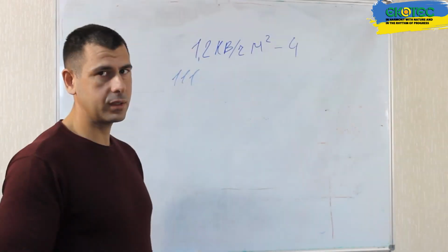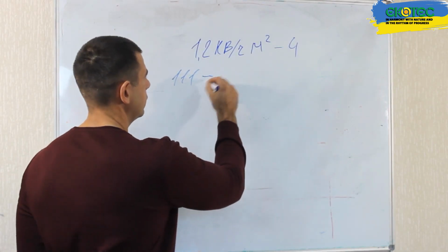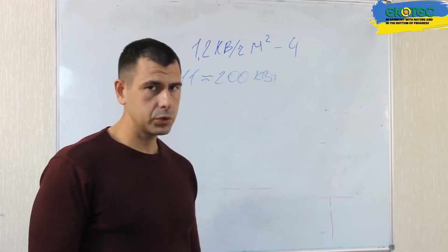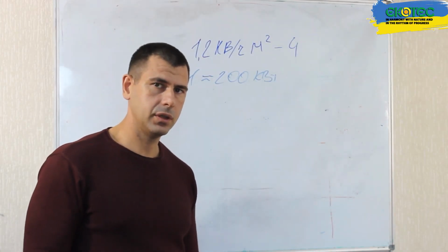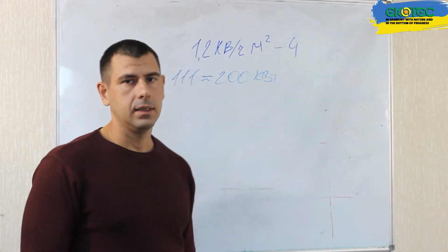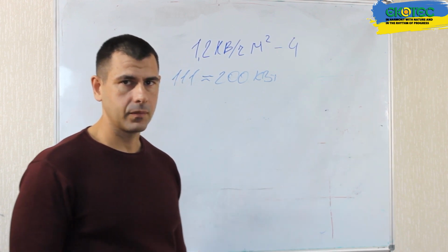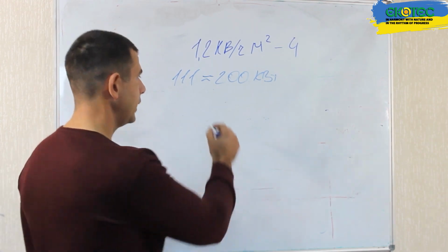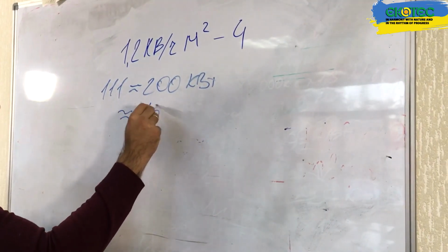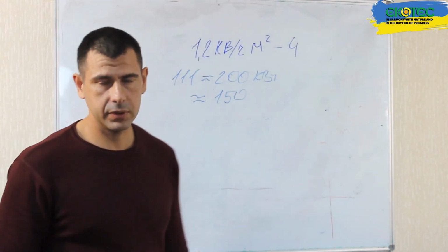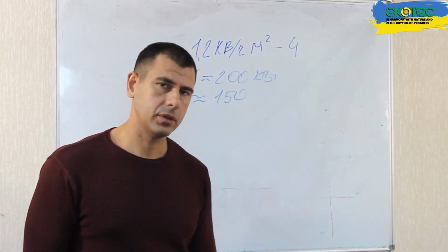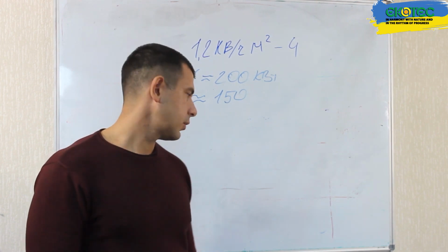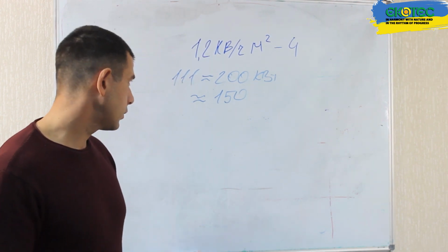Secondly, if it's 10 degrees outside, the heat loss of our 6x40 meter greenhouse would be 43 kilowatts. The greenhouse loses 43 kilowatts per hour, so with 150 kilowatts, we could maintain the temperature for about 4 hours. Thirdly, if it's 25 degrees outside, with a temperature difference of 43 degrees, we'll lose 63 kilowatts per hour. So, at most, this amount of heat would last 2-3 hours.